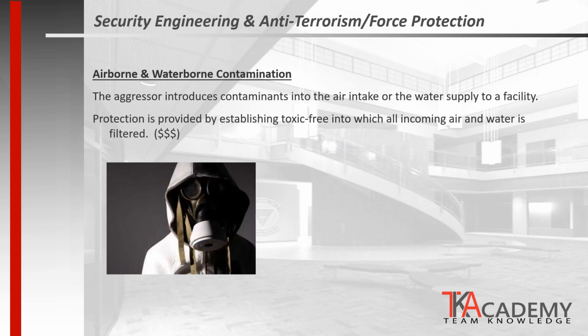The final aggressor tactic category is airborne and waterborne contamination. This occurs when an aggressor introduces contaminants, such as toxins and poisons, into the air intake or the water supply to a facility. This is very difficult to detect, and the best protection is prevention. Protection is provided by establishing toxic-free zones into which all incoming air and water is filtered, but this is a very costly method to implement.